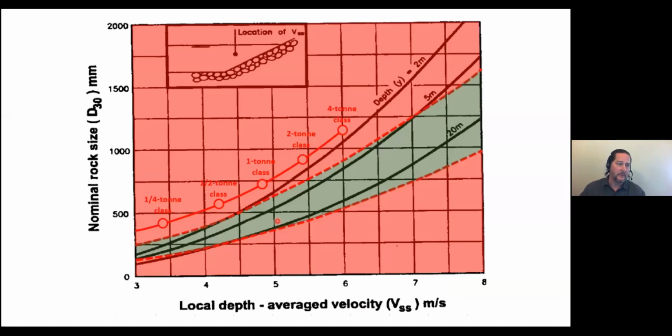And I'll highlight the zone of applicability here for these equations that were used to derive these curves, and also plot on here the riprap classes. And this is in response to Marty's question, I guess: using a velocity-based versus a shear-based approach can have drastically different results as far as the recommended size of a boulder that would stay in place in the case of a flood wave arrival. Now, again, think about this in terms of people, buildings, and vehicles, and what it would take to move it.